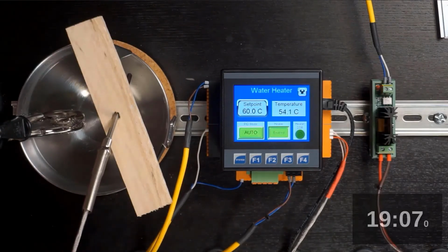You can see that now. The solid state relay is on longer and we are now headed the right direction in terms of temperature. So let's watch this and see how we do as we approach the set point. We're approaching the set point and let's see what kind of overshoot we get. So it looks like 6 or 7 tenths of a degree was our overshoot on this first time through.